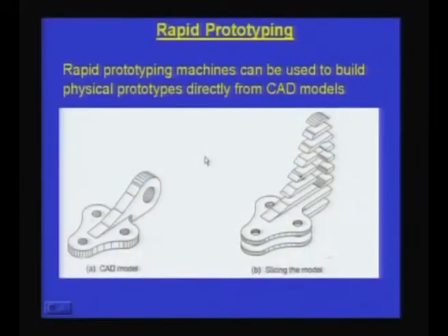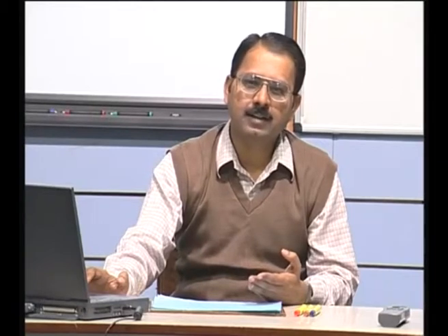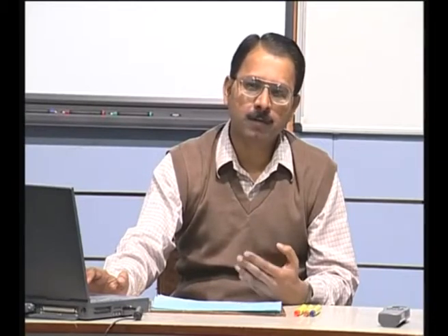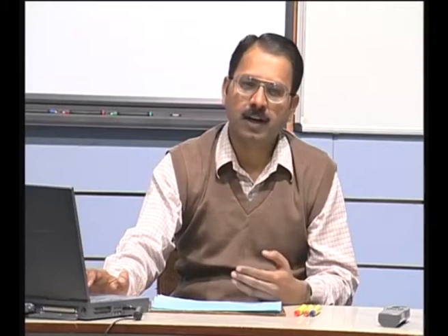In fact, a smaller version of rapid prototyping is also available, called a concept modeler, which I can attach to a computer. Once I have a design finalized, if I want a physical prototype of the design, I can just say build the component, and the design is sent to the rapid prototyping machine or concept modeler, and a physical prototype comes out after a few hours or a few minutes depending on the size of the component, and one can visualize it.